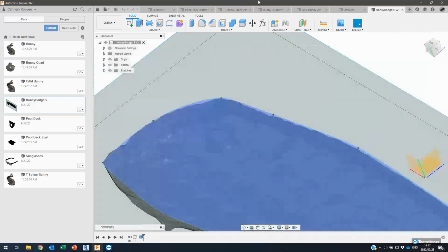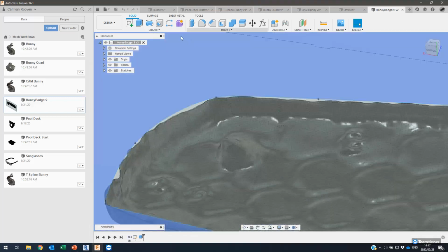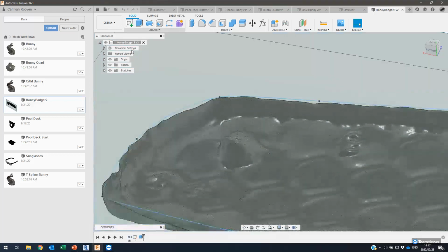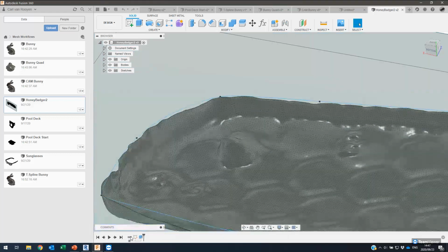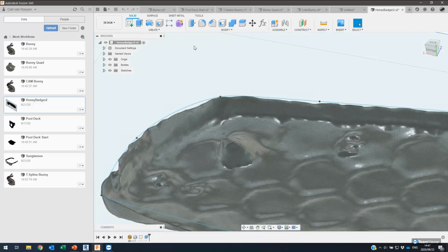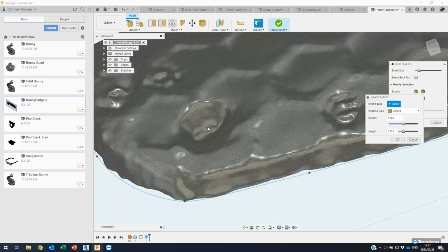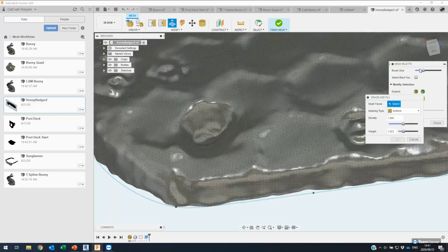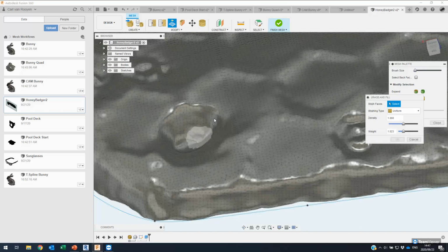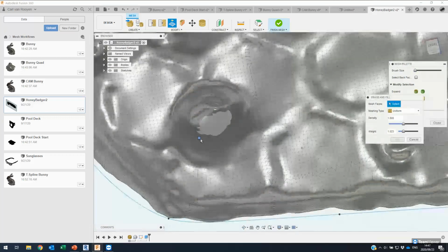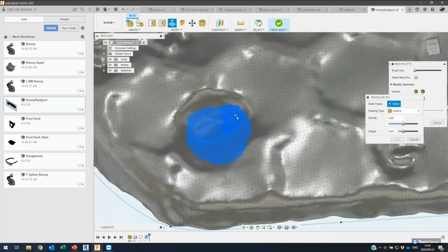This mesh does have some cleanup that I haven't done on it. You'll see that there is a bump there. But once again, I could quite easily go and edit the actual mesh itself and do something like an erase and fill. I set the brush size down quite small here, go in there and erase. This was a hole in the handle for a lanyard to clip through.